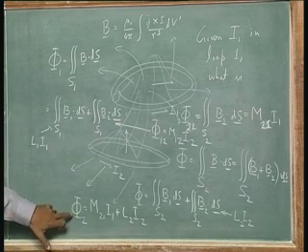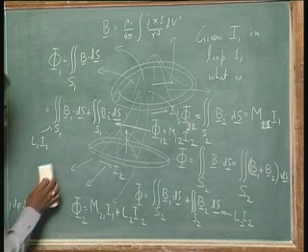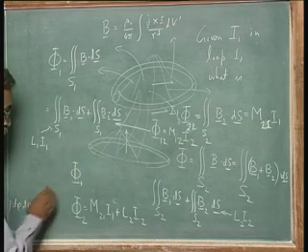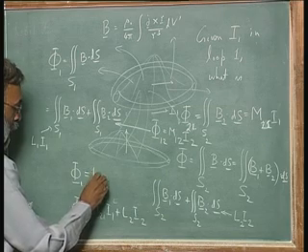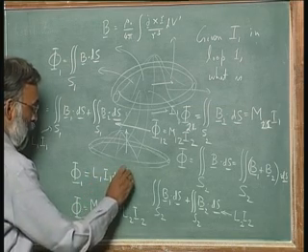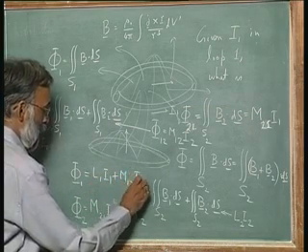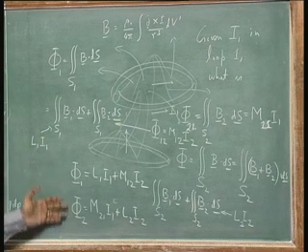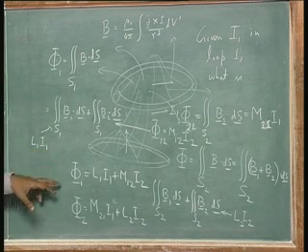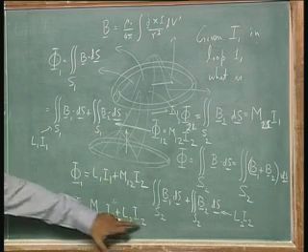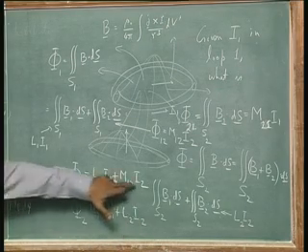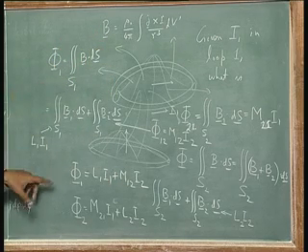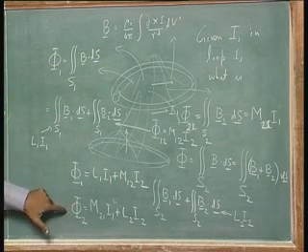So, corresponding to this equation, I have another equation. This equation looks like phi 1 is equal to L1 I1 plus M12 I2. Now, you can see that this is a matrix equation. I take all these currents I1, I2, maybe if there are more coils I3, I4, and out of them I generate a number of fluxes.